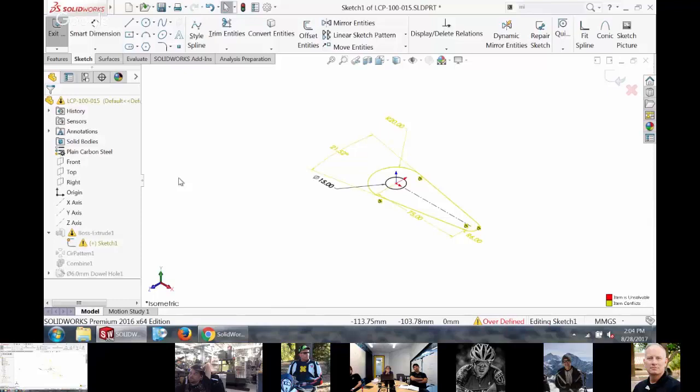There's several different kinds of errors. There's a red error, which it can't begin to even figure out what you're talking about when you see a red geometry in your sketch for the error. When you see yellow or brown, this color, it's just unable to solve it. It knows what you're talking about, but which one do you want? Do you want this to be 20 or do you want that to be 21? They're in conflict with one another.